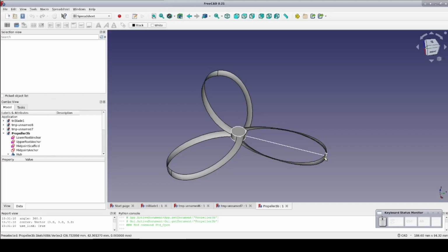Fortunately, parametric CAD is very much an iterative process. We can add additional profiles along the length of the blade to more tightly control the pitch. So let's begin. We can more tightly control the blade pitch along its length by passing the sweep through additional profiles. The additional profiles will be clones of the blade profile mapped into place. We will need appropriate reference points for the mapping.